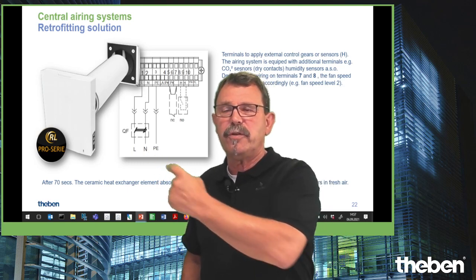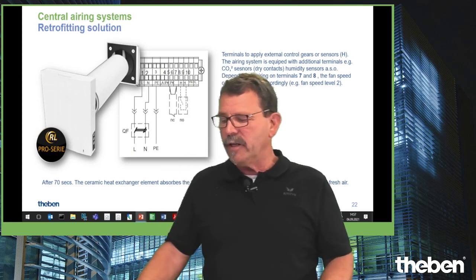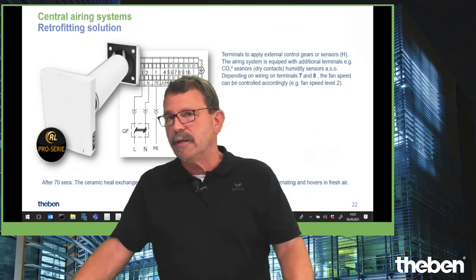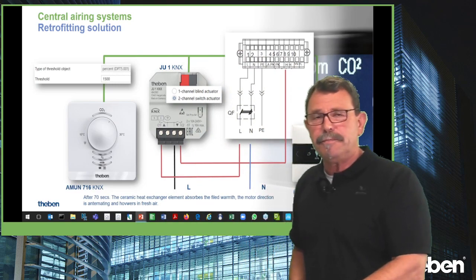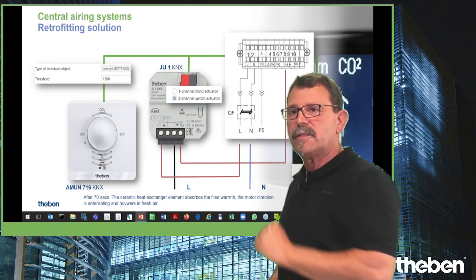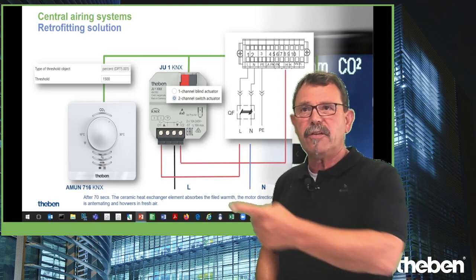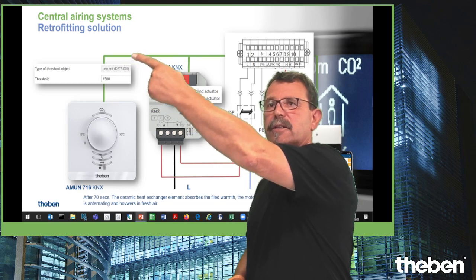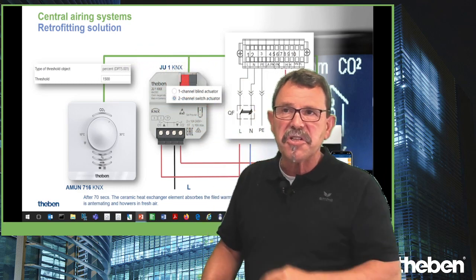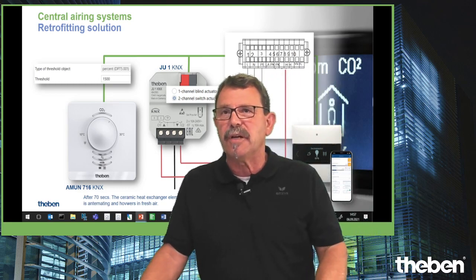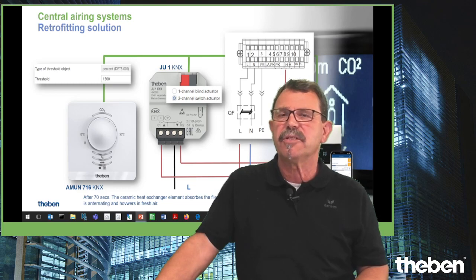And here you have the master switch, so on/off. And what you can do finally now, you need an actuator. An actuator from the KNX side, and the solution looks like that. So you have here, for instance, the CO2 Ramses 7/16 from Theben, giving on the KNX side the current ppm value. In this case, for instance, 1500 ppm. So there's quite a heavy load on the CO2 side.